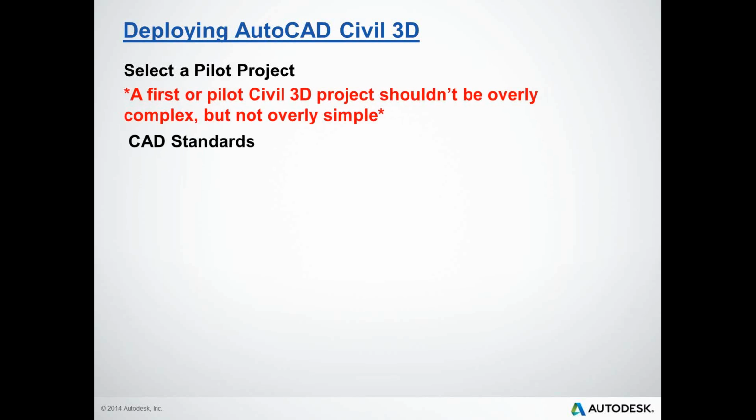Secondly, CAD standards. Everyone has somewhat of CAD standards established at their company. But seriously, before launching Civil 3D, you need to know what CAD standards are. In Civil 3D, much of drafting is done automatically. You have graphical elements of Civil 3D, entities defined by a Civil 3D style. For instance, Civil 3D knows the layer, the plot, the parcel line, what it's based upon. Everything is represented with the Civil 3D style.